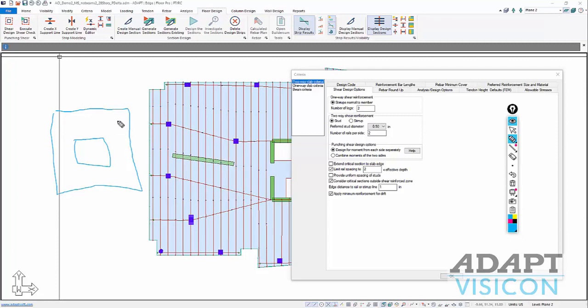That is to say that the actual shear stress is less than the allowable shear stress provided by the concrete. At that point, when no additional reinforcement is required, we'll call this layer 10. We will actually recheck layer 10 at its exact position, but we simply cut off this leg and this leg, and we base this now on an octagonal shape. So we recheck this section, again at d over 2 from face of column. That's at this layer based on the rectilinear shapes.